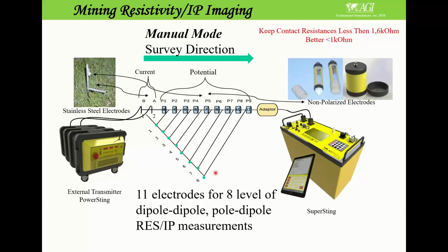When you get the decay curve of your measurement, you can also follow it on the tablet. If you are especially doing it manually, you can see that decay separately, and if you're satisfied, go to the next one. If not, you repeat the measurement. You change parameters of the current injection or improve the contact resistance, which is a very important part of this webinar today.